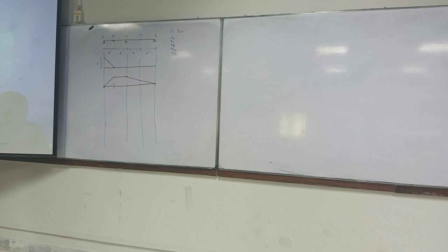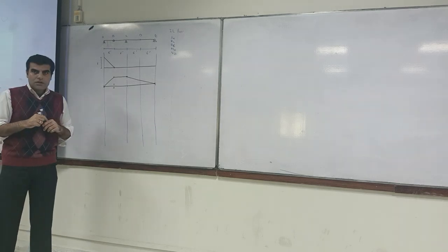Can there be another point which can move up and down? There can't be another point which can move up and down. Can there be another point which can rotate? There are two pins in the center, so there are 2 points there. B is hinge and C is pin support, so there are 2 pins.